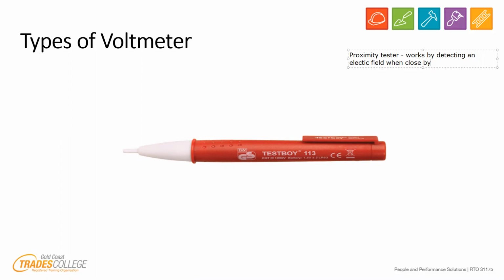When we're testing voltage, whether with a multimeter or with a volt stick, there is a test process that you must go through, and I'm writing it up here in capitals. This will follow you around your electrician life and in all of your practical exams. Remember this saying, get it tattooed on your head if you want to, because if you do, then you won't have an accident. Prove, test, prove. What does that mean? So this is the process.